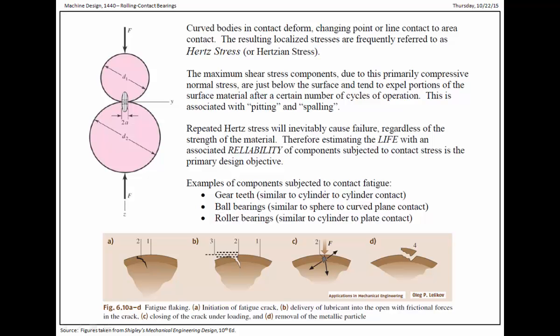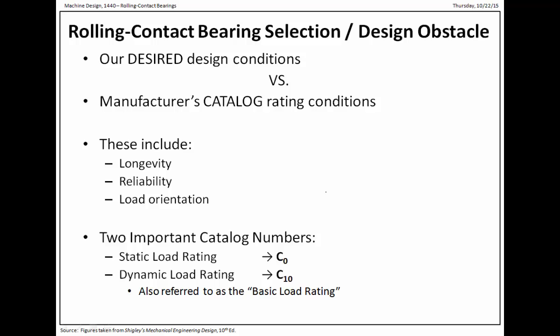And okay, this is just a summary of the things I've said already. The fundamental thing we want to do in bearings and ball bearings is to establish the load-life relationship. The issue at hand is we have our desired conditions for our design, how we want to use the bearing, but we're given only a small amount of information from the manufacturer. They've come up with some numbers that they provide you, and they're not going to be identical to how you're going to use the bearing.